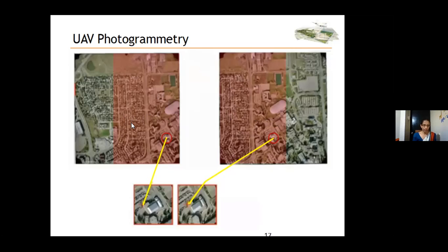So when taking the photograph, you have to consider overlap between your photographs. That is the most important thing when working with photogrammetry.